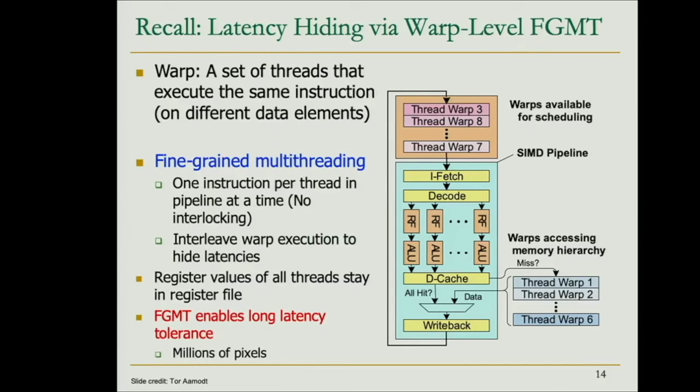This is what the warp scheduler does when it goes to this L0 or L1 instruction cache, reads one instruction, and starts decoding it to issue onto the lanes. So we decode it, and then we have these scalar pipelines in parallel, and each of them represents one of the SIMD lanes inside the GPU core.